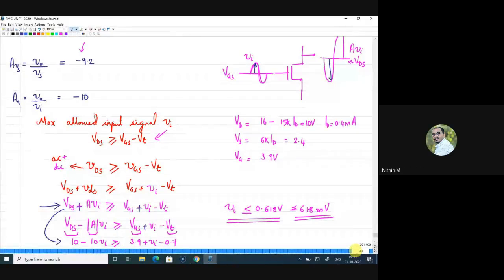Right? So is that what you expected, or do you have some other doubt? No, sir. Like we found the maximum input voltage, right? Is there some maximum output voltage or something like that? Maximum output voltage: we can actually limit it. The output maximum can go even up to the supply limits. But the problem is whether, at that condition, the transistor remains in the proper region of operation or not. So in order to bring about that condition, we have to force it on the input side.